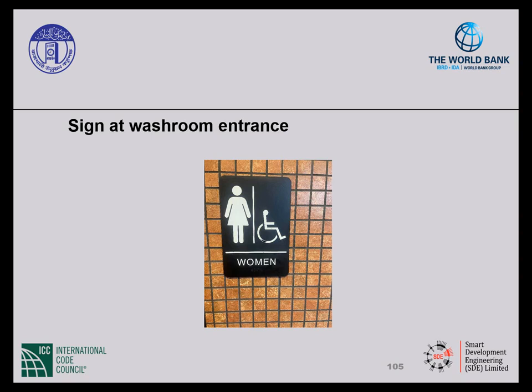You also need to provide signage outside of the washroom entrance. And that signage should comply with section D.26.2 and D.27, which we'll talk about in a minute. But as you can see on this sign, you provide the symbol of accessibility. There is a raised pictogram and letters. There should be braille underneath the letters, and we'll talk about the requirements for all of that later.